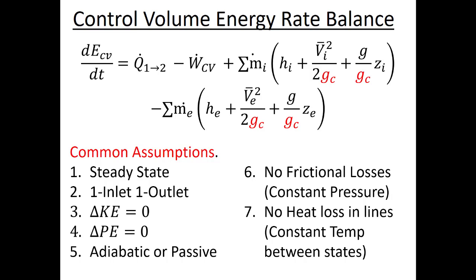So if you're doing a Rankine cycle and you have mass that's coming out of a turbine, and then eventually it goes into a condenser, we'll assume that the temperature and pressure, for example, are the same coming out of the turbine and going into the condenser. Although there will actually be some losses in the system there, we'll say that those losses are small relative to the other terms that we're calculating, and that'll really cut down the number of states that we have to fix throughout the problem.